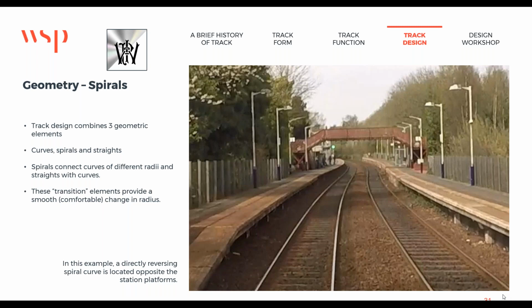computational power, but eventually at the end of all that, there's the hydraulics that push the coach over, that tilt the coach, and it has to tilt it to the right value for the curve to get to that kind of equilibrium. And it doesn't actually achieve equilibrium, it achieves something the same as the ride quality in a normal train. So you still get some centrifugal effects, but not the same centrifugal effects you would get if the tilt mechanism suddenly stopped working and the train was still trying to travel around that curve at that speed. You would definitely feel uncomfortable, and you would definitely lose control of your wine glass as it slid up the table quietly.